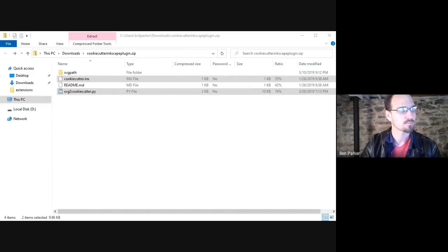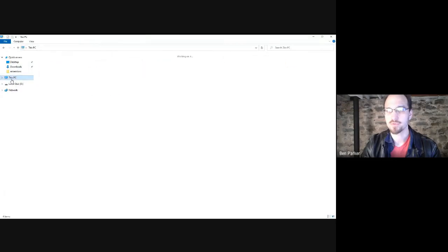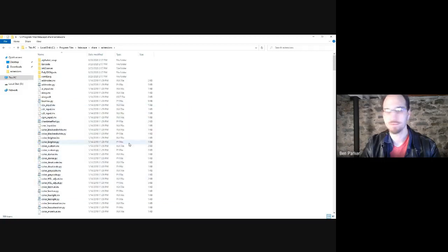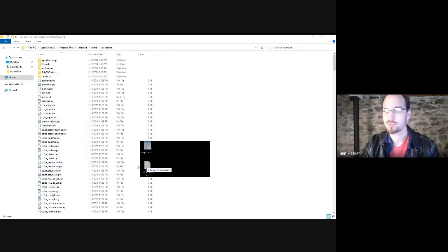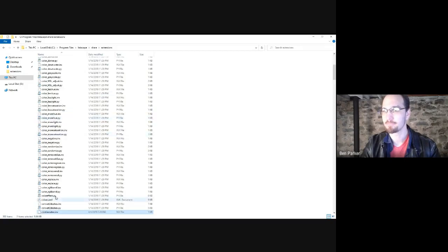Those. So we're going to drag that into This PC, Inkscape, share, extensions. You've got all those. You drag the .py and the .inx files right in there.